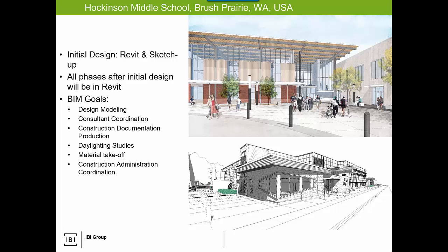Daylight studies, it works beautifully, right? Revit has some built-in daylight study capabilities, and you can bring it into other systems, it can do it, but something very fundamental: what if I model the glass as an opaque solid panel? Guess what? Daylight studies failed right there. So something as simple as that. I built my curtain wall in the BIM tool, but I didn't call the glass glass. It thinks it's brick. Daylight fails. So remember that.